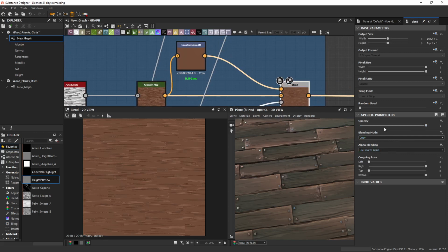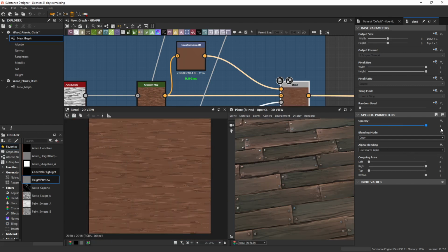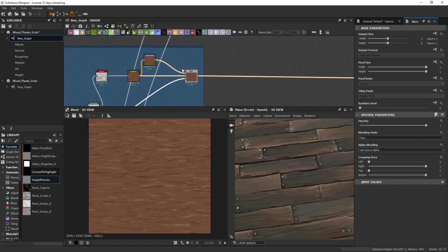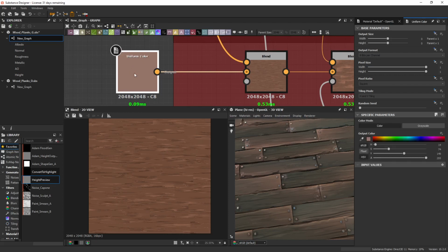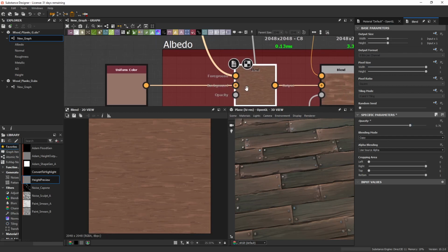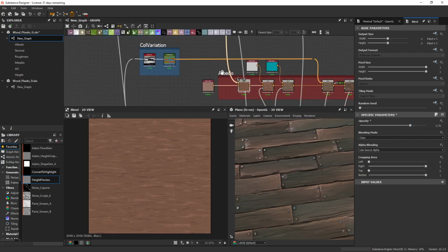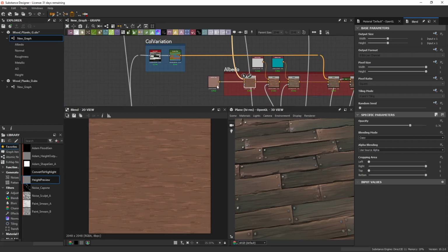mask out some. So before this, it's a bit too noisy. It would be nice to have some areas that are broken up a bit more with more flatter areas like this. And then all that's doing really is we pick a default color and just overlay this texture on top. And you can play around with this and the blend modes as well to get what you want. So we're not using this as the base, it's more of an addition to your base color.